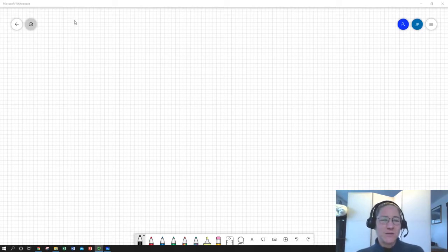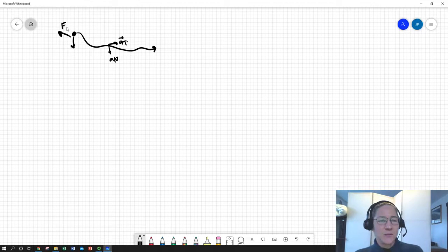So typically when we were looking at particle motion, if we had, say, a particle undergoing some kind of motion, we can look at its motion, get acceleration, tangent and normal on a path. We can look at forces acting on the body, maybe in the x and y direction of a coordinate system. And we can draw a free body diagram, and we can solve for the sum of the forces in either the i hat or j hat direction as equaling the mass of the particle times the acceleration in the x or y.